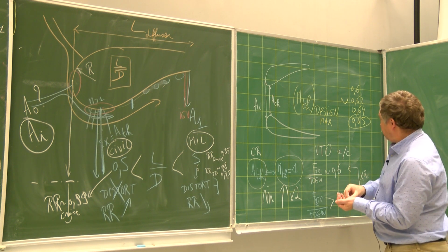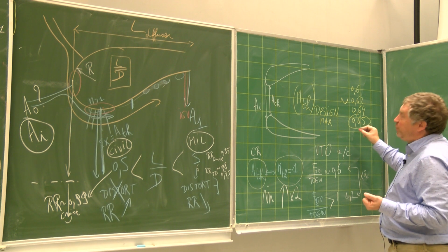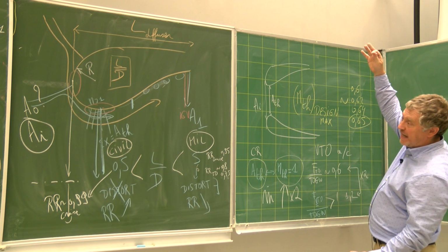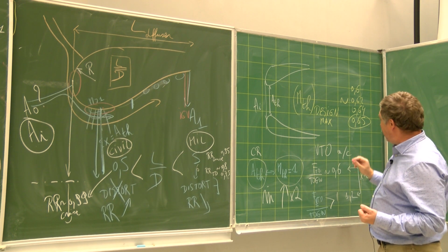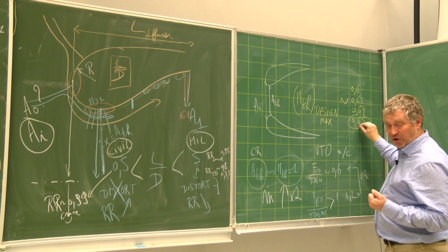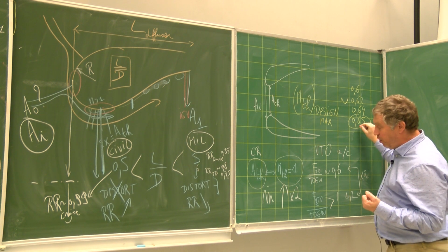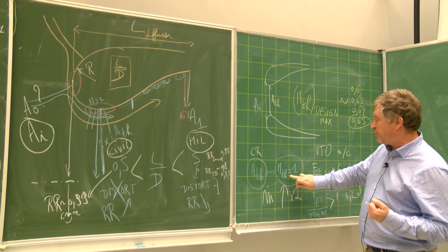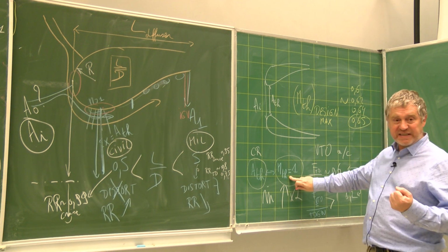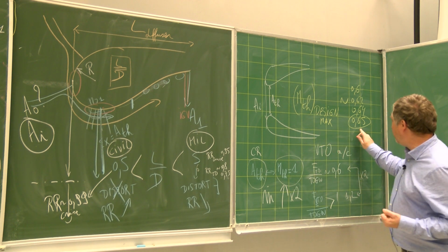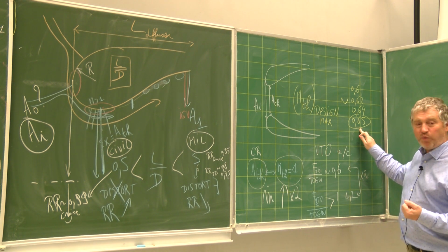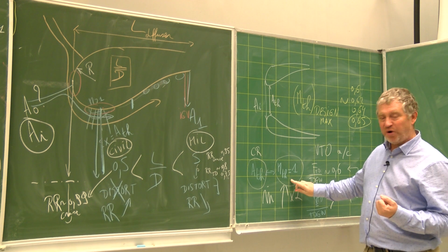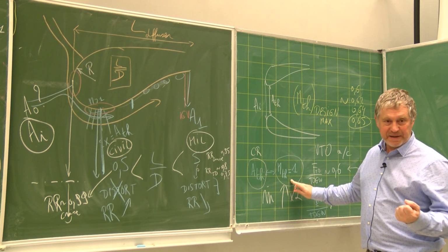But not high, but not too small, otherwise the intake is becoming enormous. But you see that if you take 0.65, how can you increase the thrust, so the mass flow rate, so the M throat by a factor 2? This is impossible, because if you increase that by a factor 2, you have 1.3, and we can pass only with 1. So it's impossible.